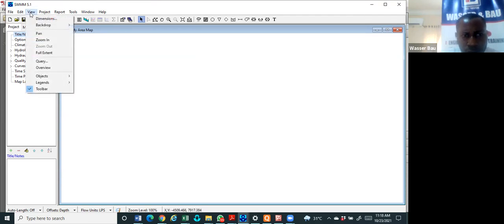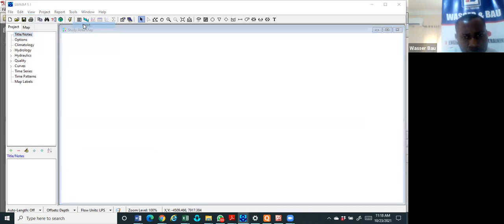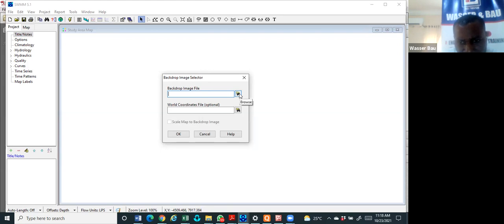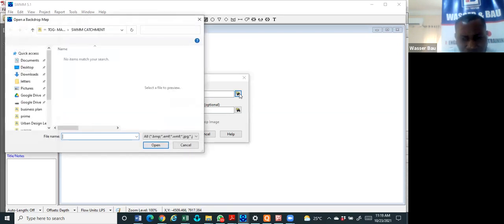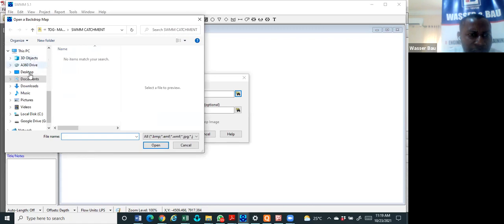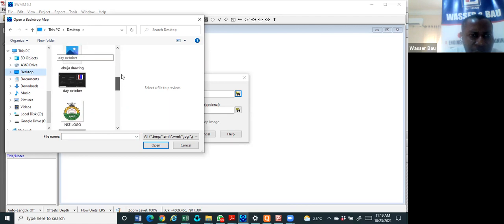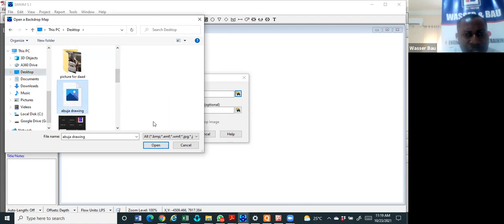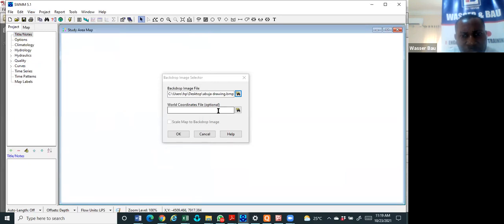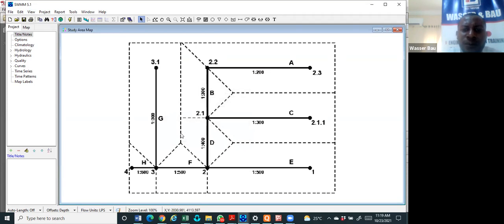So I'll go to view, backdrop, load. I'll look for it through this flyout. I'll browse for it. It's on my desktop. So I'll go to my desktop and I will see Abuja drawing. Look at it. I'll click on it. I'll click open. If there is a coordinate, some georeferencing that is involved, I'll click this, but there's no georeferencing, just forget about it. I'll click OK. It has been imported. You grab it.